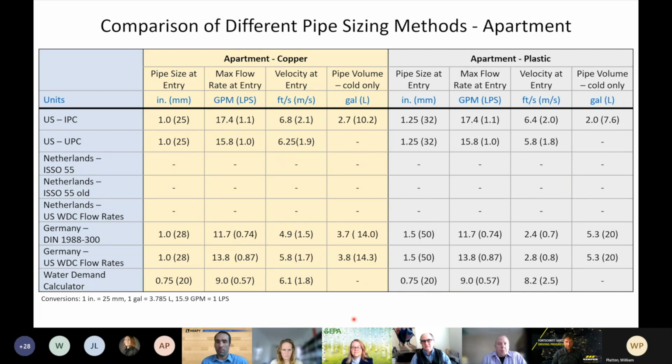With oversized pipes that we see all the time. I joked before, we've always had the moniker, no one ever complained about having too much water pressure or too much hot water. But now we know that this oversized idea of piping is wrong because it has the side effect of bacteria and waterborne pathogens breeding in that. So what we try to do is just skinny the pipe and be a little more aggressive on the sizing to get it closer to reality flow rates versus code and Hunter's curve.